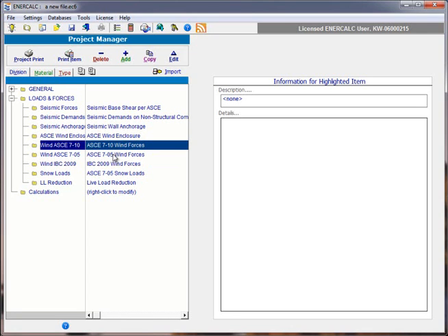And it's a significant departure from the predecessor module, which is the ASCE 7-05 wind forces module, because the one that's based on ASCE 7-10 actually goes beyond calculating pressures, and it goes all the way to the level of calculating forces, both story forces and base shears and torsions. So if your building is one that can be approximated by a box shape that is of dimensions B by L by H, then we think that the ASCE 7-10 wind forces module is going to be a welcome tool, because it will take those calculations for wind forces so much farther than its predecessor did.